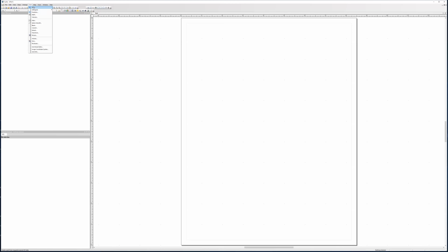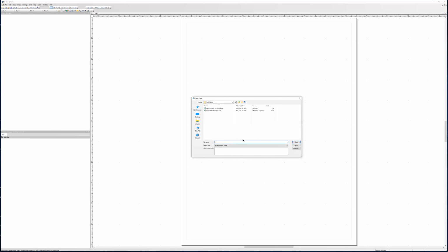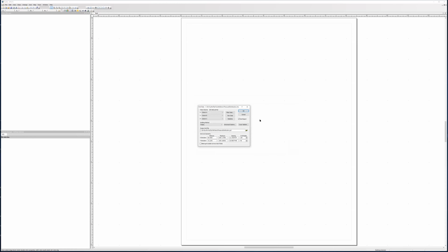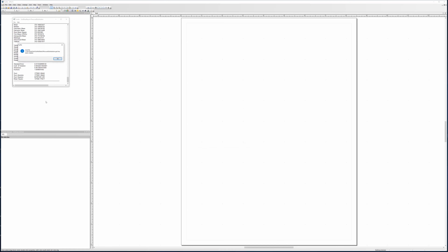Now, so let's start the process itself. So I click on gridding, and I take the data. I take this example data file, and SURFER will open it up. It makes some statistics. It will say, okay, this is X, Y, Z maximum, minimum values, and this will be the file where it writes the results. I just click on OK. I have the file already, but I will overwrite it. And then SURFER makes a run.